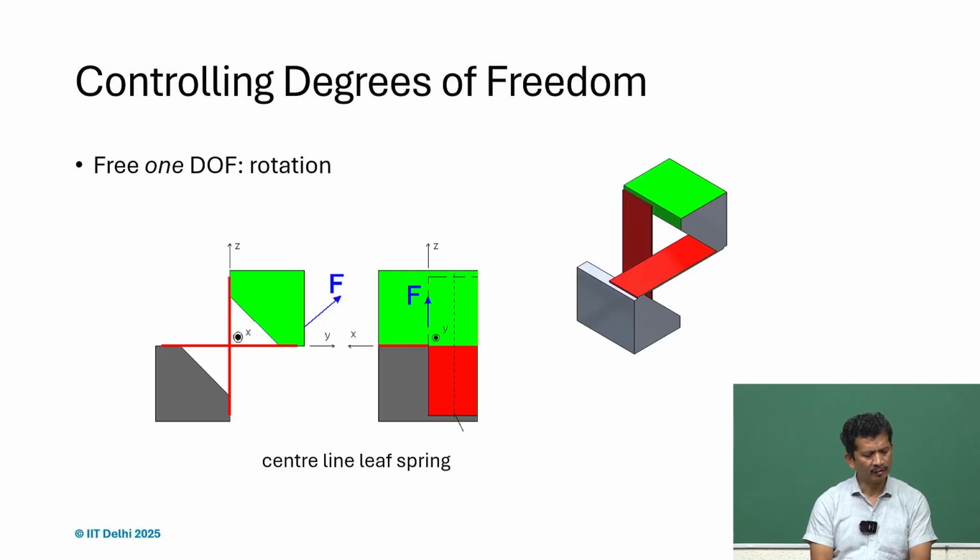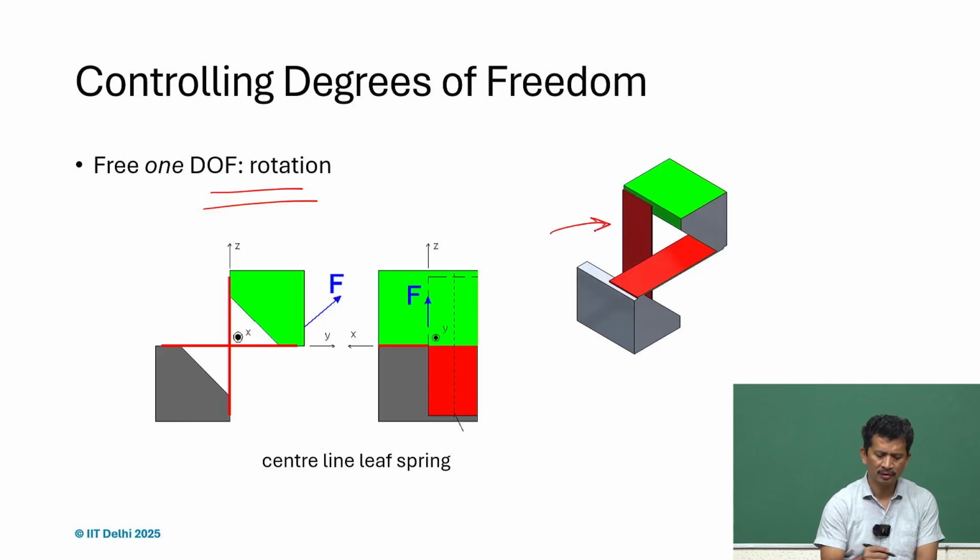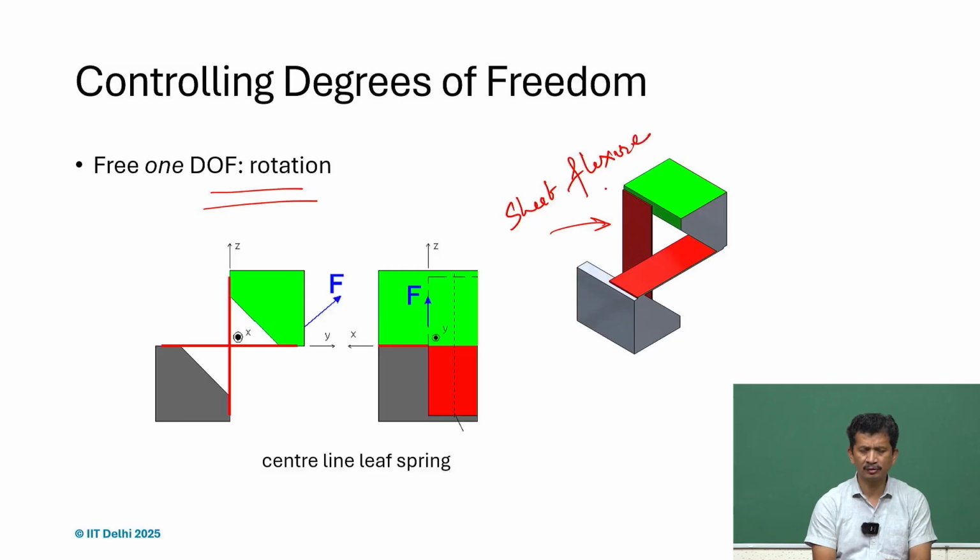So, moving on, what we realize is that some of the designs are very simple, and we can use very simple artifacts or elements. So, not just the articulated links, but we can also use sheets, which we later refer to as sheet flexures, or leaf spring we call it, but yeah, some people may confuse it when we say leaf spring. So, let us better use the term sheet flexures.